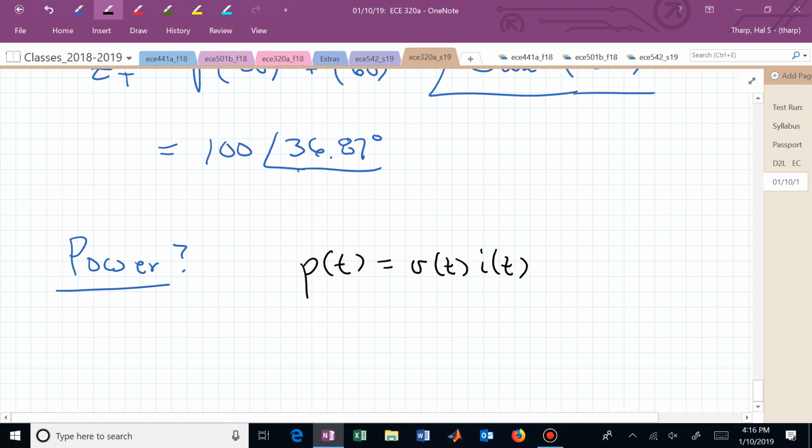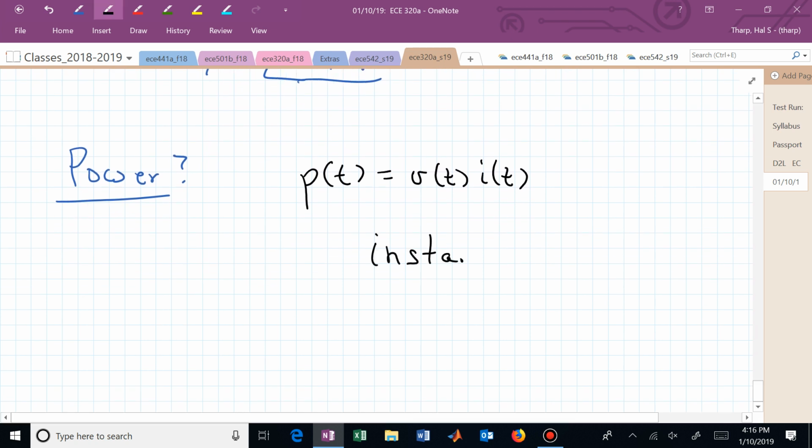But we can talk more comfortably about what it does on average. What's the average power? This is actually the instantaneous power, but we could calculate that. It's going to be really fast moving, because we've multiplied a cosine 377t, and i is also a cosine 377t. There's maybe a phase shift between those because we have energy storage elements, these inductors. And when you take the product of a cosine with another cosine, you start looking at your trig tables, or your formulas. But we can simplify that by looking at these in terms of phasors.